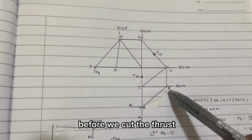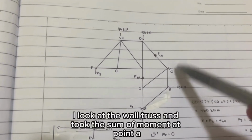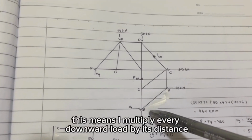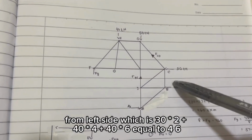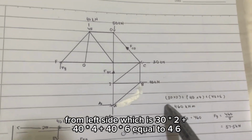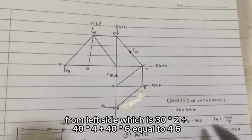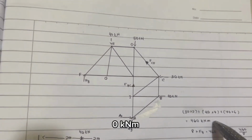Before we cut the truss, we need to know how the ground is pushing back at the supports. I look at the whole truss and took the moment at point A. This means I multiply every downward load by its distance from the left side, which is 30 times 2 plus 40 times 4 plus 40 times 6 equal to 460 kilonewton meter.